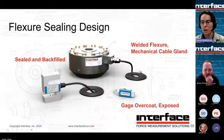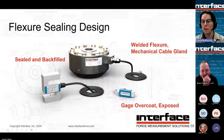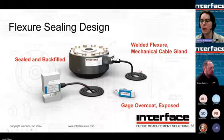Then, on the other side, the right side there, the MB, that's pretty much exposed. So it still has a gauge overcoat, a conformal coating that we put on almost all of our load cells. But besides that, the wires and stuff like that are only protected by that cover. So if you put a screwdriver or something in there, you could ruin the load cell.